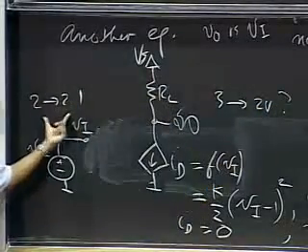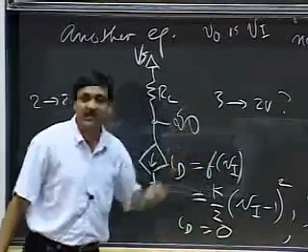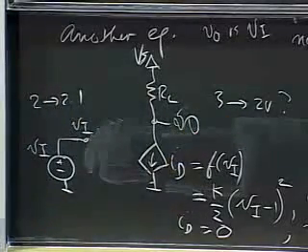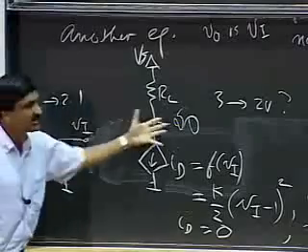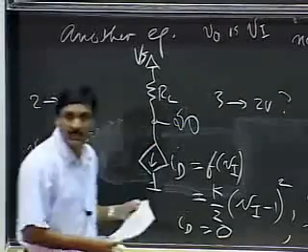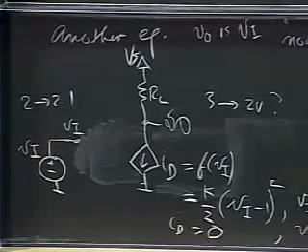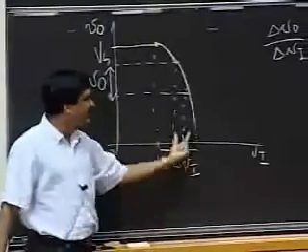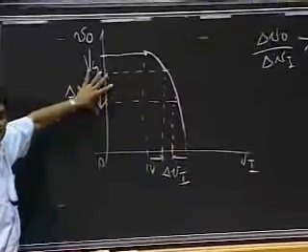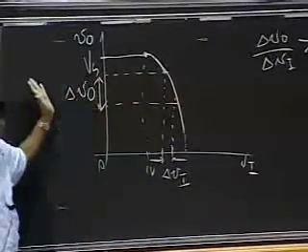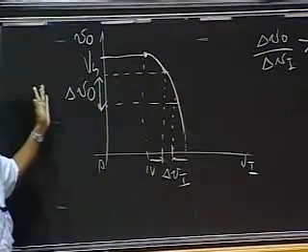So for a 0.1 change here, I'm going to get a bigger drop here, say from 3 volts to 2 volts, giving me an amplification in this little circuit. We'll see this again and again, and you'll really understand it. So I have a small change in the input, and a corresponding larger change in the output. So I've shown you an amplifier.